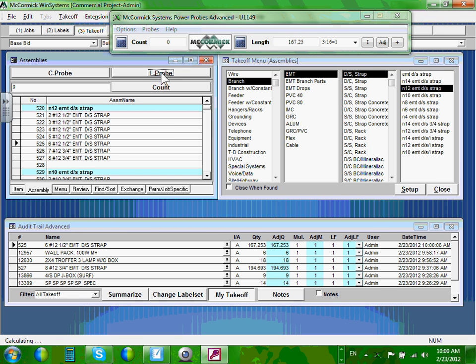Now you can go as deep as you want. Start looking. Have we taken the boxes? Have we taken the hangers? Have we taken this one? I want you guys to focus on the big picture. Big pictures are branch circuits right now, fixtures, and devices. Cool? Don't get hung up on every single little thing. Otherwise, you will go nuts, and we don't have the whole time to putz around. As you go through and become familiar with the system, you start digging deeper and deeper into what the assembly has and what the assembly doesn't have and what I need to add.